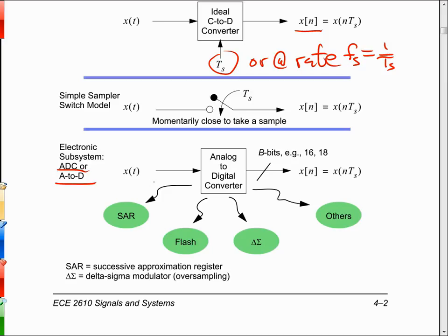You can reduce the error down, right? So delta sigma tends to work that way, and it's the newer technology. It's not something that can operate at really high conversion rates because you have to oversample. You might oversample at 64 times oversampling.